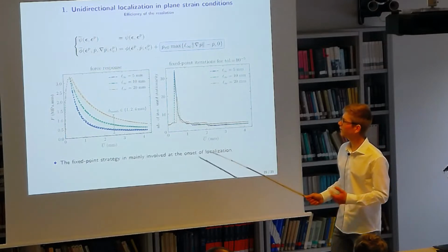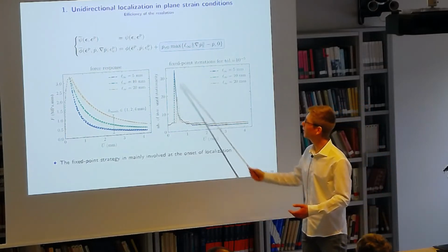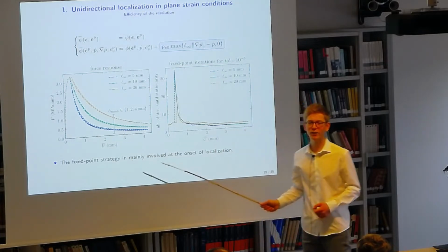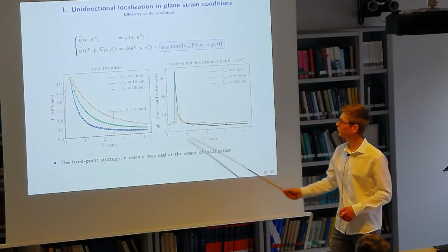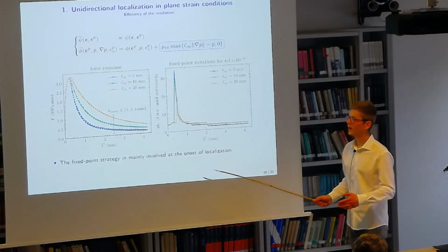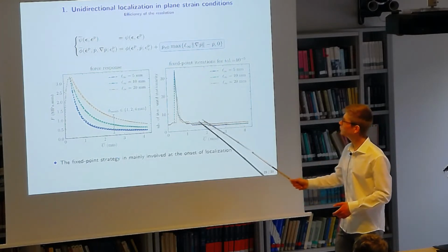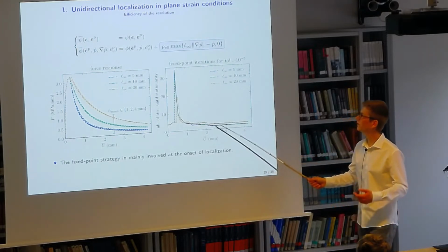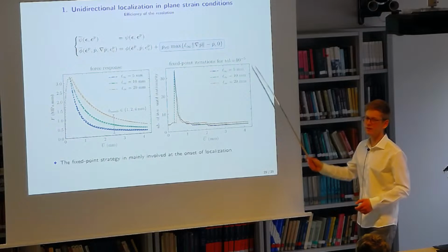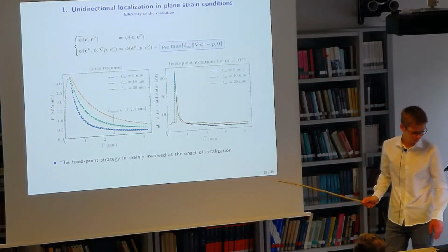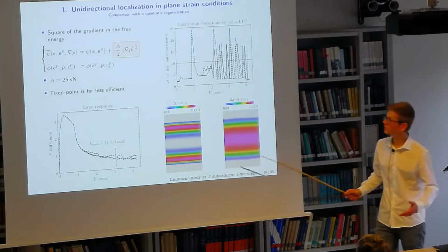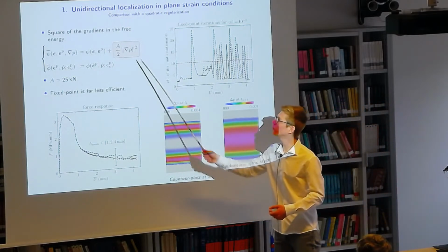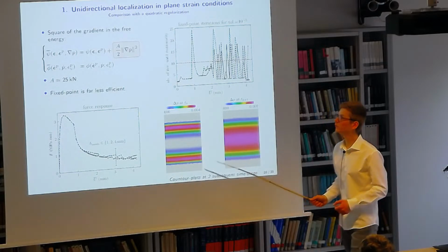What we can observe is that it is mainly costly and involved at the onset of softening and, at the same time, the onset of localization, at about a displacement of 0.5 mm. After that, it doesn't cost anything to use this fixed point iteration strategy, since after one or two iterations, we have reached the tolerance criteria which have been prescribed. This is interesting because it can be compared to the performance of a more usual regularization by a quadratic term in the free energy.